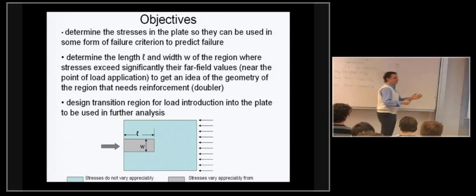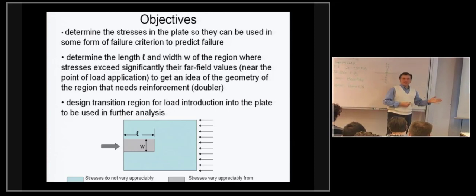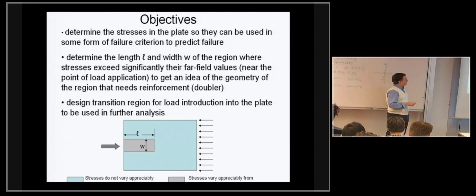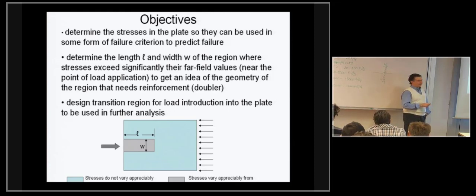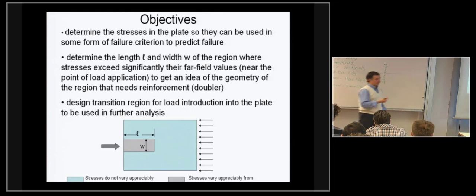It's because we're saying, okay, if I know that I'm going to have stiffeners terminating, most likely right where the stiffener terminates, which is at this location here, the skin, if I designed it just to take the load in the distributed form, would definitely not be strong enough. So I would need to reinforce the skin, and we select obviously to reinforce the skin locally because making the whole skin twice or three times as thick, while it would work, adds weight.